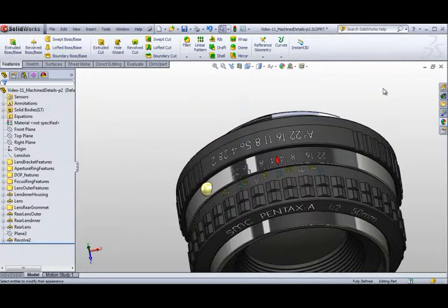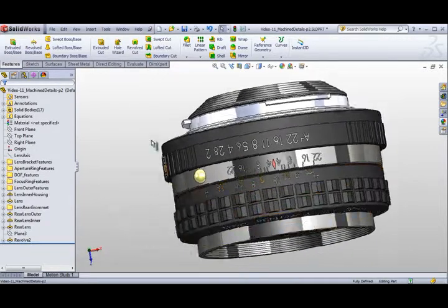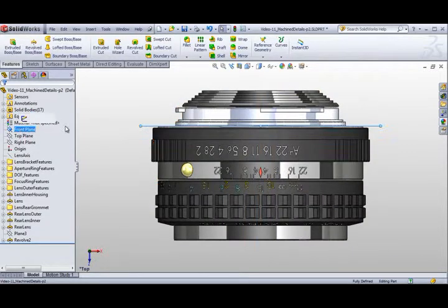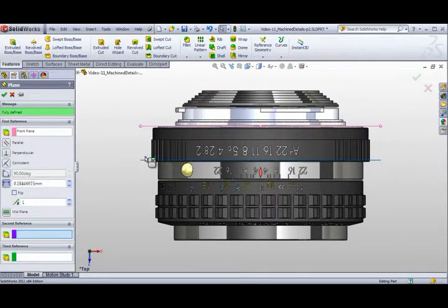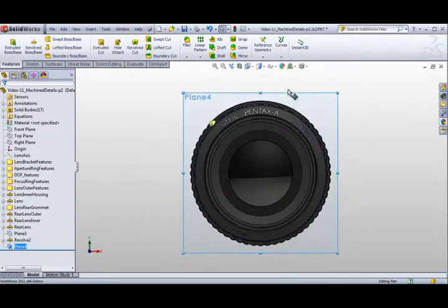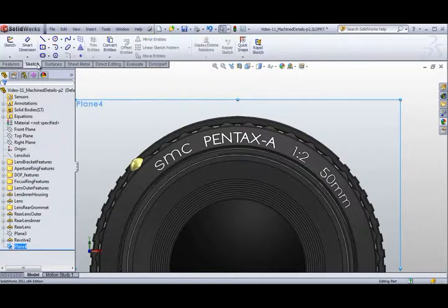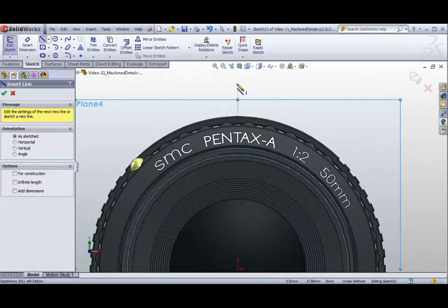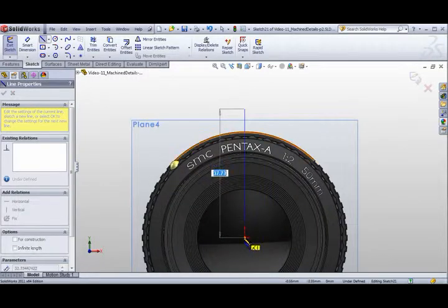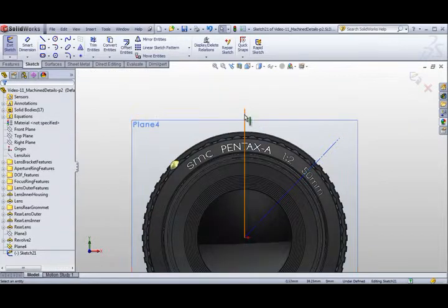And now we're going to repeat that process all over again to create another one over here. It's going to look very similar, but slightly different. So take that front plane, control drag to duplicate it so that it's centered where we want our little dot to be. Look at the normal view, sketch tools, line, draw a vertical line down to the origin and then back out again. Make sure both of those are construction geometry.